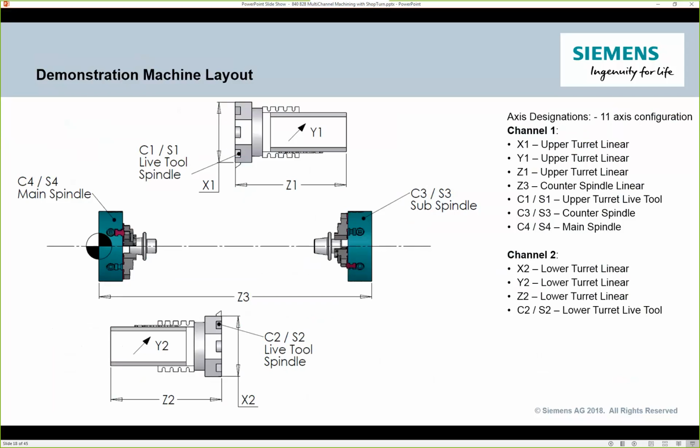I'm spinning an end mill. That would be a velocity mode. If I'm positioning something, that would be more of an axis mode. So that's where we have the C or the S, depending on the mode you're in. But in their case, S1 is always the upper tool. S2 is always going to refer to the lower turret and the spindle in the lower turret.